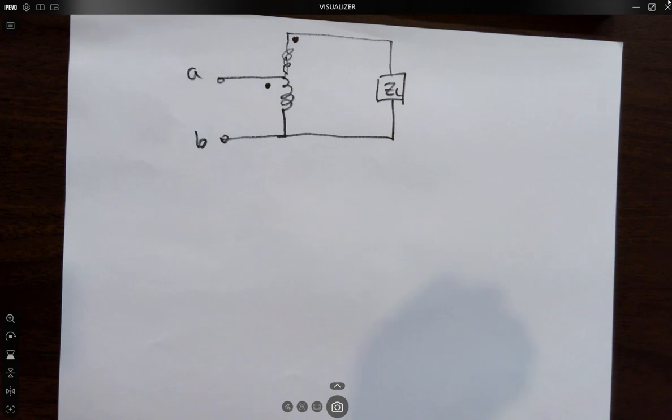And I have used a solar panel as a receiver. For example, I'm playing music from my phone, and I amplified that music sound, and you directly connect that analog audio signal to an LED, so the LED will blink depending on the audio signal's intensity versus time, and that blink is the light signal received by the little solar panel I bought from Amazon. So the solar panel receives that light signal. There's nothing connected, okay? No hardware connected.